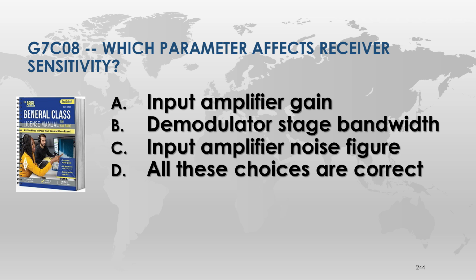Demodulator stage bandwidth. If I got the bandwidth too narrow, I'm not going to hear it. So there's two of them that affect it. And the input amplifier noise, there's two, oops, I guess it's D. The input amplifier noise figure, that's how much noise is getting amplified. All of those are going to affect your receiver sensitivity.